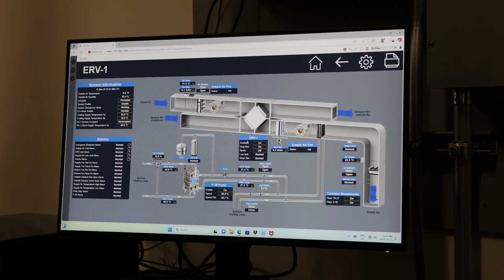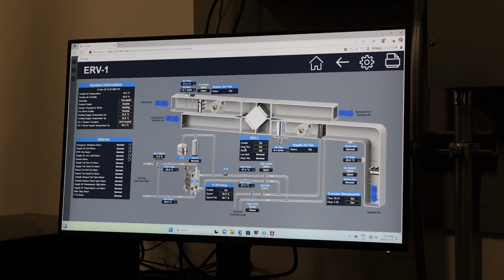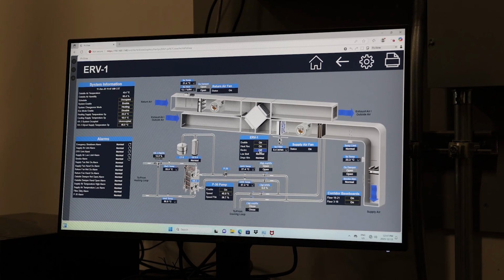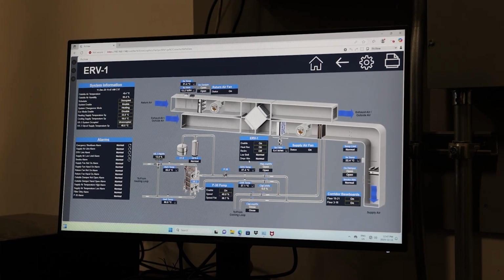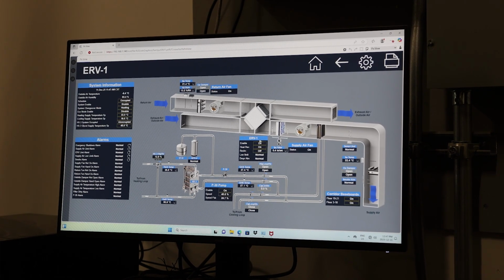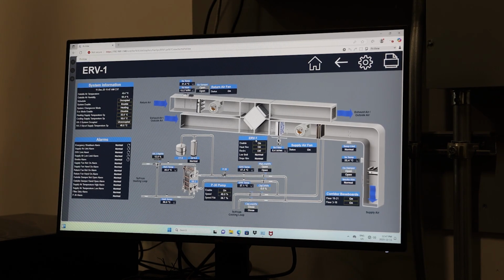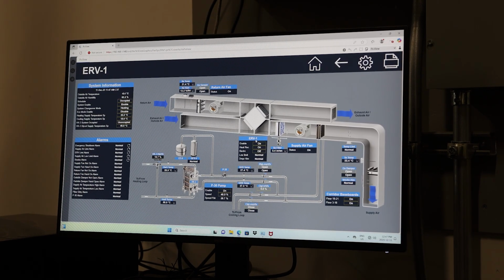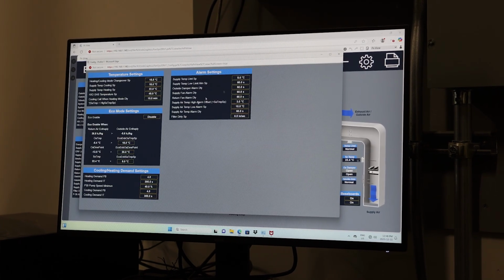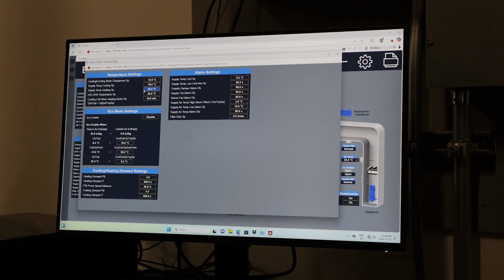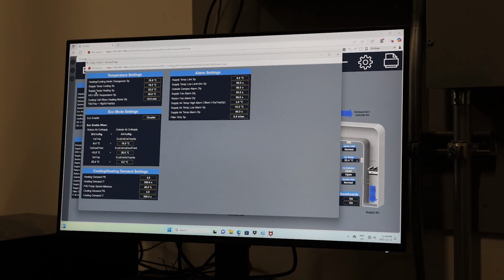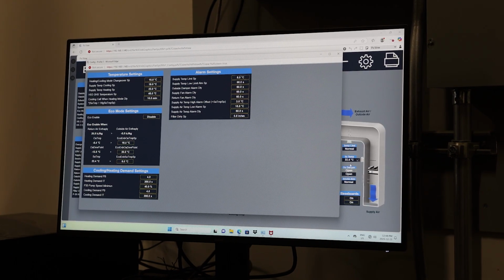To control the HRV BMS, we will have the enable, heat recovery mode, recirculation mode, low alarm, and the damper alarm. All those signals we pick up from the ERV panel I showed you earlier. And from the configuration page, we have some temperature setting. So let's say in the summer mode or in the heating mode, we have a supply heating temperature set point, which is 22.